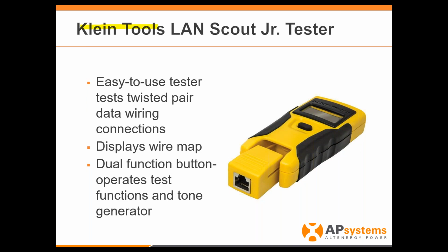Again, not brand specific, could be anything, but this is a fantastic tool right here. Again, I always recommend a hardwire connection to the ECU. It is just the most reliable. We always talk about reliability of modules. We talk about reliability of inverters. No one ever talks about reliability of the internet connection. And as we all know, that is equally as important as anything else on that roof, because you're going to get a phone call if the internet is not working. And the last thing I want you to do is roll in trucks to fix Wi-Fi connections.